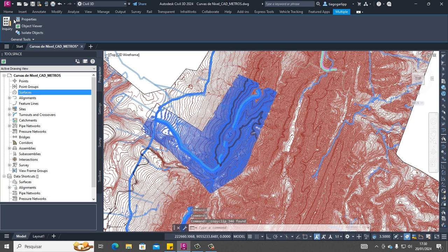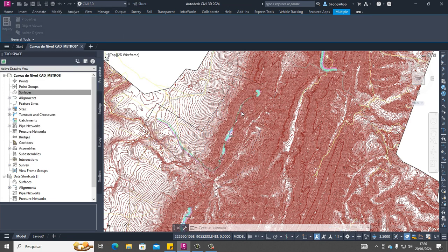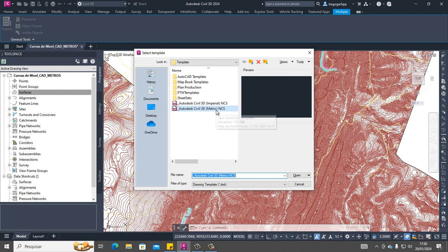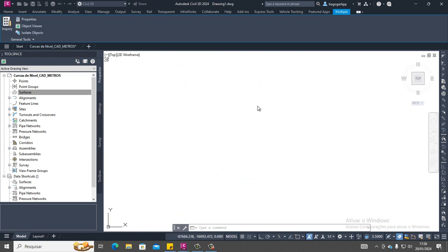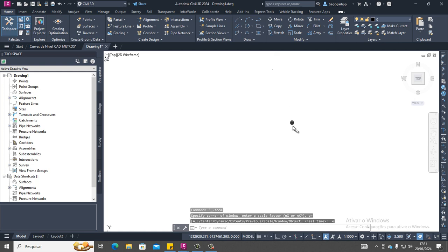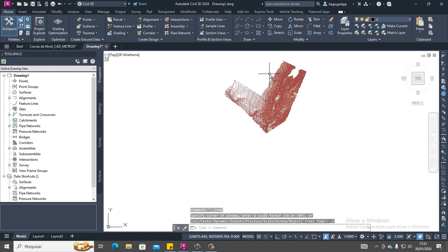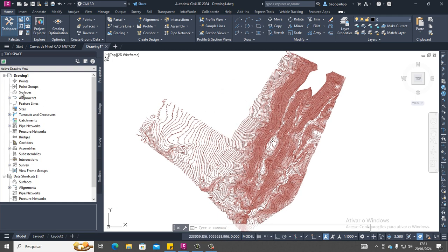Now I will open a tab in Civil 3D and create a new drawing based on one template, match system, as I mentioned before, and click open, and paste in original coordinates. Home tab, use paste to original coordinate, and to better look at it, use zoom extents or zoom in to focus on the area.